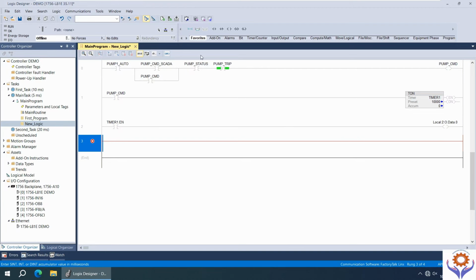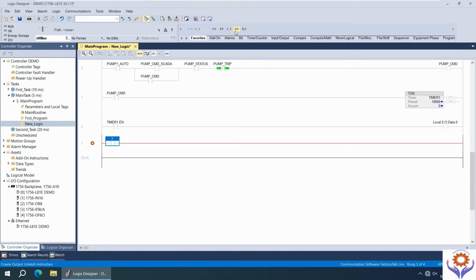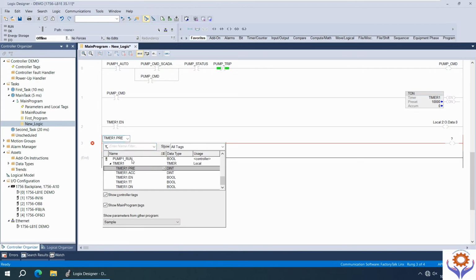And in the next rung, I created the rung, added the normally open contact, and added again the timer bit here. See here, I will check here. We have many. See, this 2 is double integer. See, now I added double integer. It will show the error continuously.